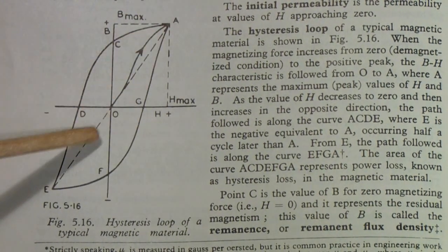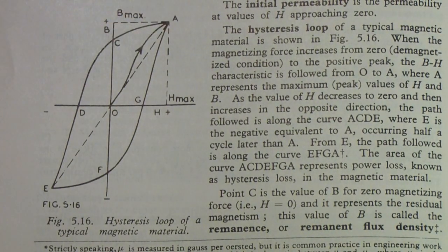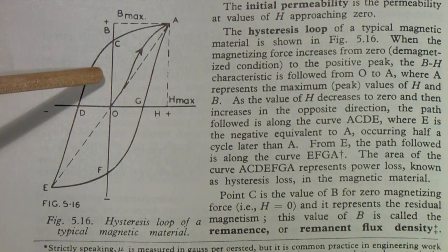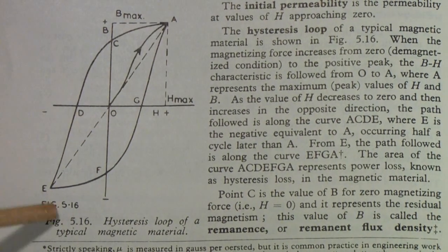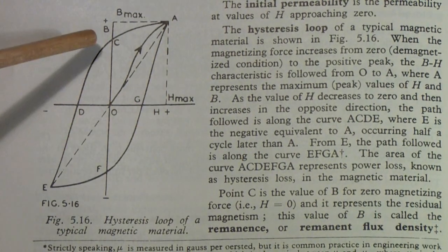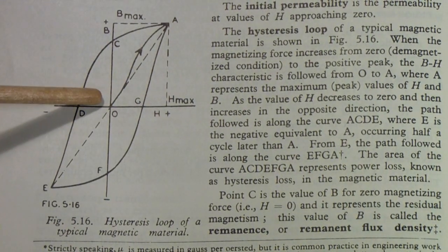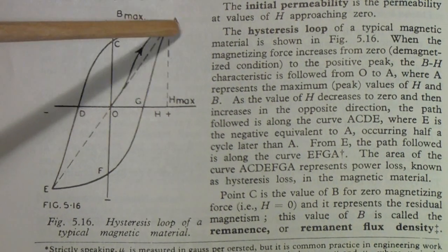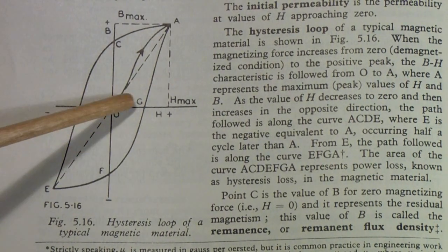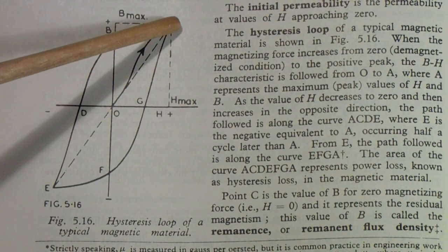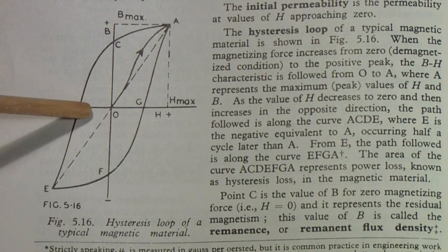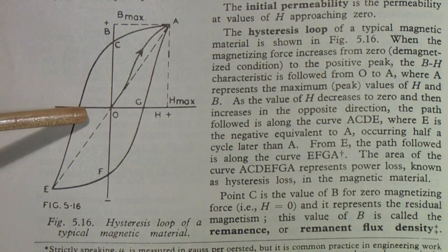Part of the reason for this is the residual magnetizing of the core itself. And so, depending on the core material you choose, this loop can be rather large and broad, or it can be a little bit more narrow. But no magnetizing material has an absolutely straight linear BH curve. In other words, as you apply current, you don't get exactly a linear amount of magnetizing in the core. This is one of the causes of problems in output transformers. We're not going to talk more about this.